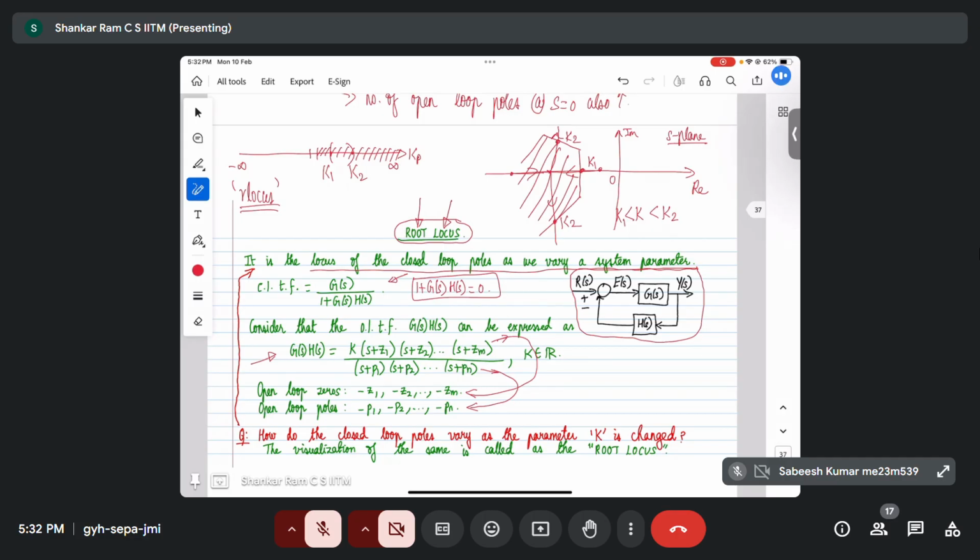Yeah. So essentially, many times, for example, if you want to control the speed of a motor, you want to design a controller which will regulate the voltage input so that you get a corresponding speed output. You can get the system transfer function, design controllers, and then use the root locus to find out a finite range of controller parameters which will do the job. So in your projects, you will do such an exercise.